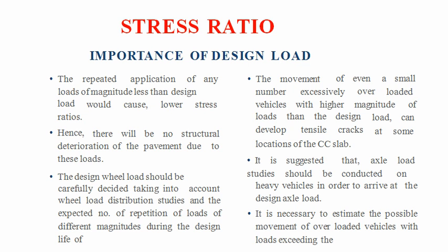The design wheel load should be decided very carefully by taking into account the wheel load distribution studies and the expected number of repetitions of loads of different magnitudes during the design life of the pavement. The movement of even a small number of excessively overloaded vehicles with higher loads than the design load can develop tensile cracks at certain locations in the cement concrete slabs. Hence, it is suggested that axle load studies should be conducted on heavy vehicles in order to arrive at a design axle load.